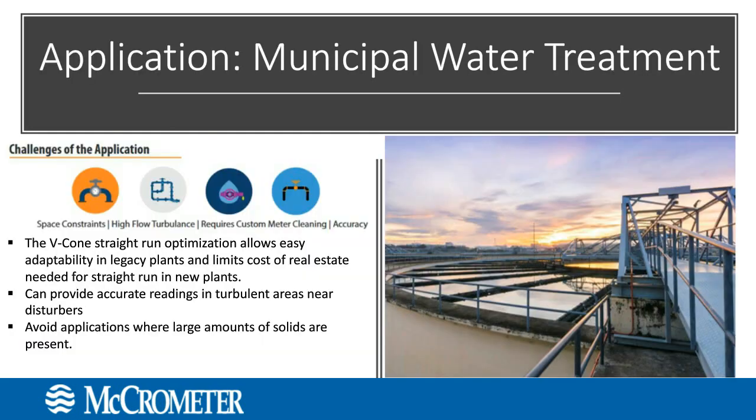We do, however, operate outside of the oil and gas industry. Specifically, we have some decent applications within the municipal water treatment area. VCone straight runs allow for optimization, adaptability in legacy plants, and limiting real estate costs needed for new plants. So, you know, even older water treatment plants might not have the real estate available for large amounts of straight run, particularly if they were built in areas that may have at the time been a little bit more rural, but now find themselves being slightly more urban.